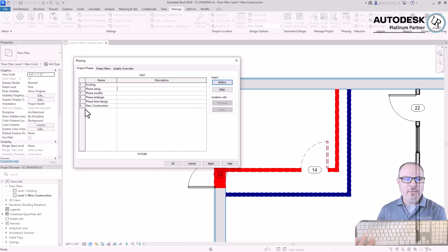However, I can share with you the more phases that you add to the Revit project, it's going to make the phasing process more complex and complicated, because each phase is responsible for an adjustment in the objects themselves, and as you make modifications to creation and demolition, the demolished content must be created in one of the existing phases or one of the phases in the project.